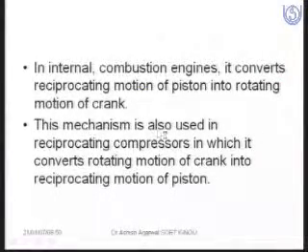The mechanism is also used in the reciprocating compressor, in which it converts the rotating motion of the crank into reciprocating motion, just the opposite of this. In the internal combustion engine, the reciprocating motion is transformed into rotary motion, while in the case of the compressor, the rotary motion is transformed into reciprocating motion. So these are 2 examples of the 4-bar mechanism.